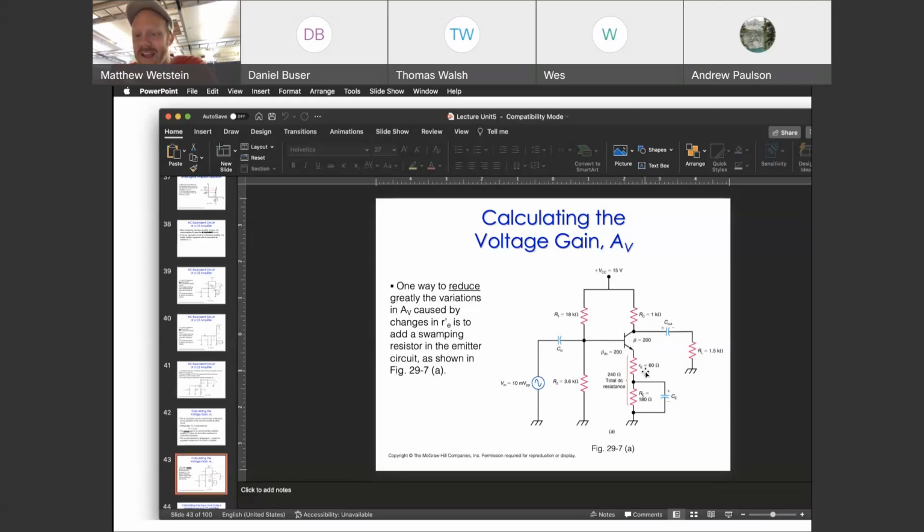So that's the gain. And that makes it a smaller gain, but it's more stable because it's driven more by a resistor than by a very tiny nonlinear diode in a solid state device that's probably temperature dependent and varies from transistor to transistor. I can buy a very precise, well-spec'd resistor for cheap that I can use to kind of set a very stable voltage point. And that's why you might want to swamp it.